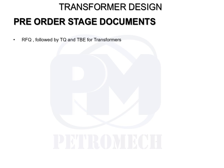For example, when I say the maximum flux density at the maximum voltage and frequency variation has to be less than 1.9, we can ask the vendor in the offer stage, are you abiding by the same as per standard or not? They can simply mention yes, yes, and if the third vendor says no, that becomes a big deviation point from the design point of view.